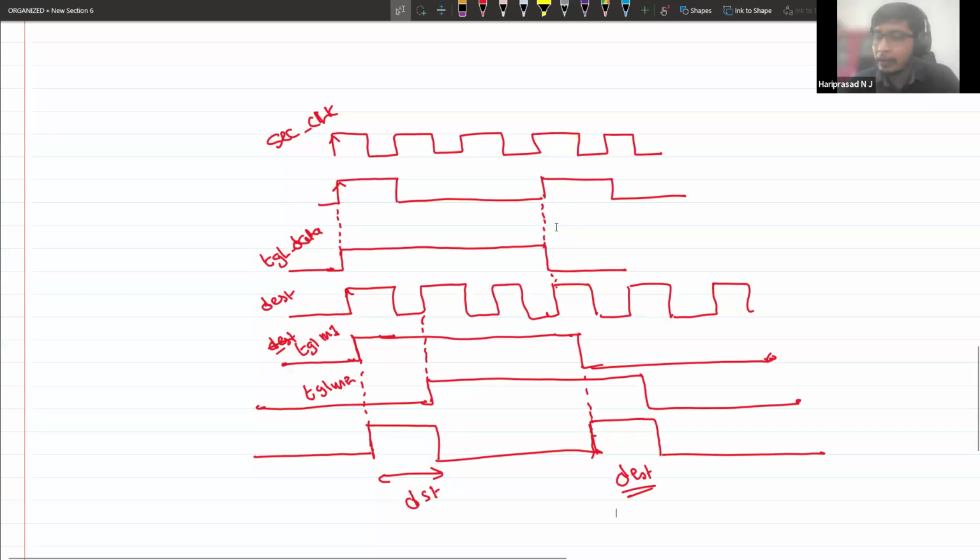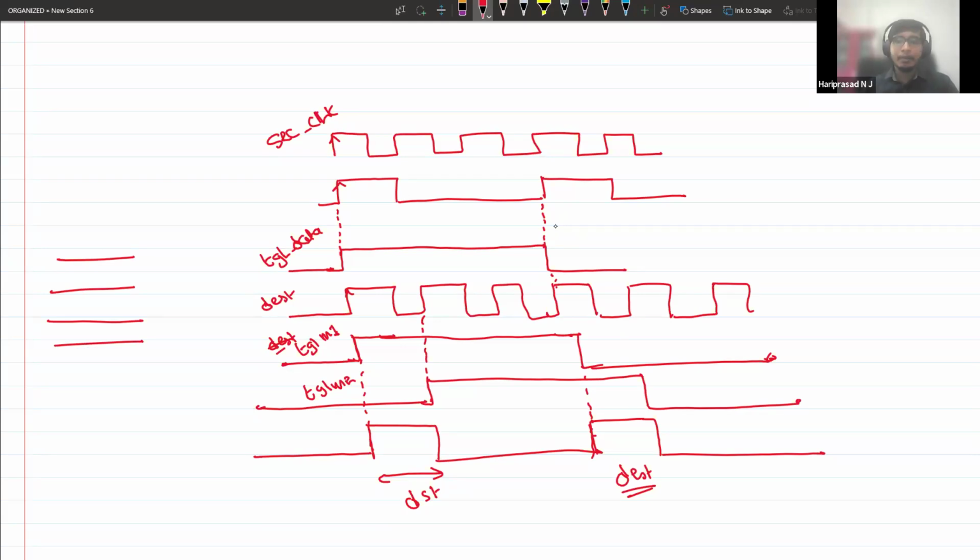Because let's say I have 16 bits of data, and I implement all these kinds of synchronizers for 16 bits of data. In placement and routing, all the flip-flops may be placed in different locations, right? So that will not be possible. Especially, that will create a lot of skew and data corruption.